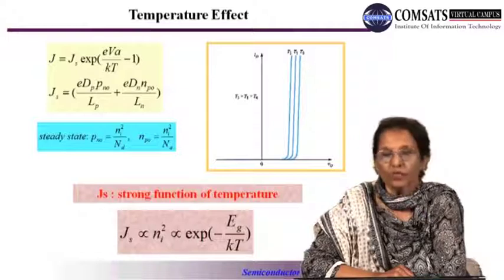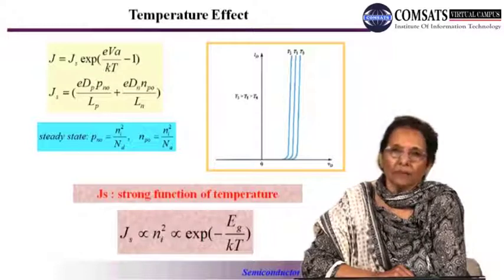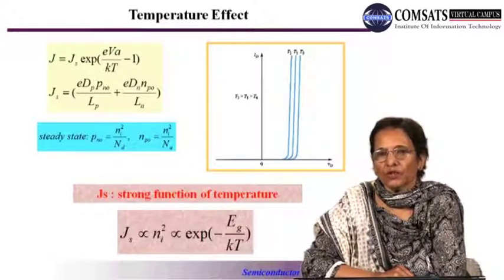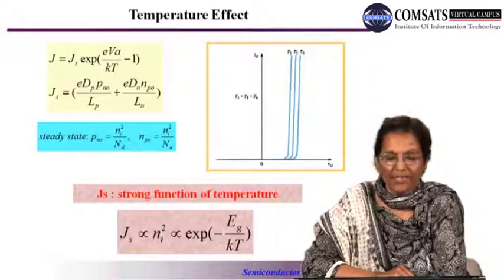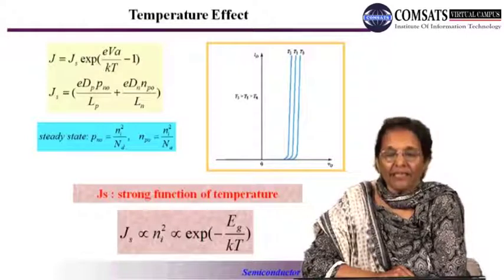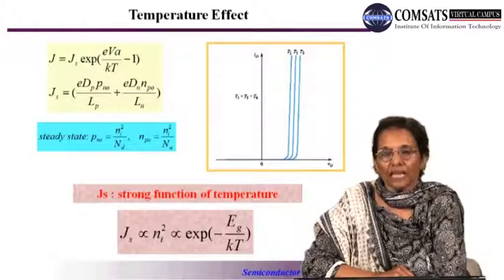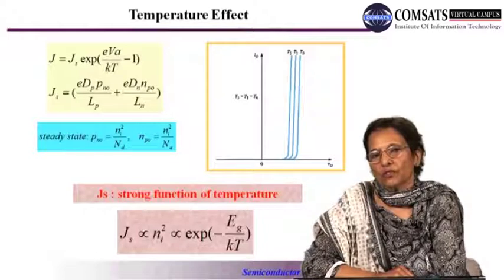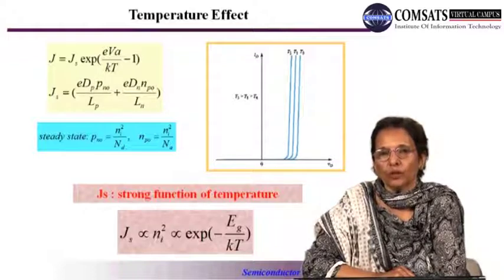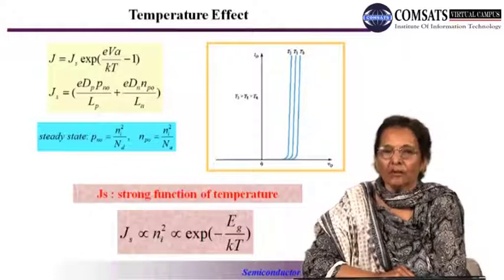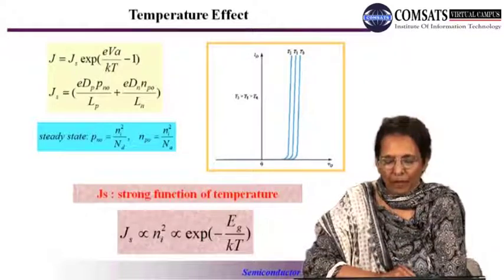The same relation, which I defined as the law of mass action, I have now expressed quantitatively: the product of holes p_n0, n referring to the N side and 0 referring to the equilibrium condition, the injected holes into the N region, and the donor concentration ND, are subject to the law of mass action. That is, the minority holes p_n0 in the N region and the majority electrons in the N region, which is the same thing as ND.